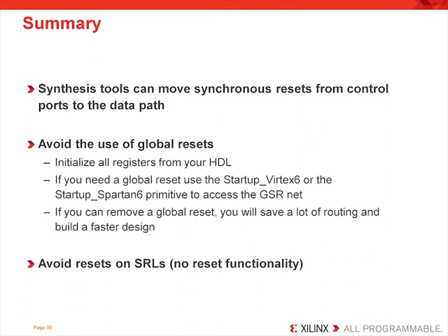Avoid the use of global resets. Now specifically here, what we want to encourage you to use is the GSR, the Global Set Reset Net, whenever possible, which is used automatically and is used to reset the device and have the system come out into a known state after configuration. So anytime you can use the GSR, you use it. But if you're building an additional reset to reset all your flip-flops, don't do that. Try to use the GSR.